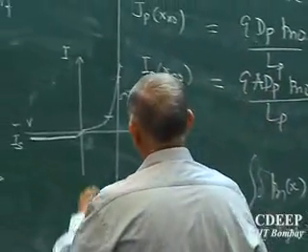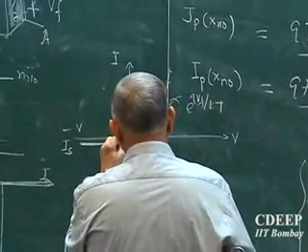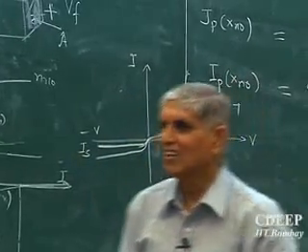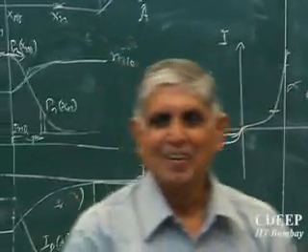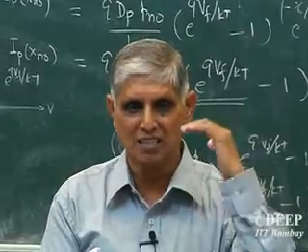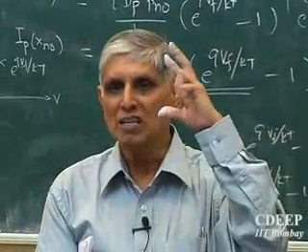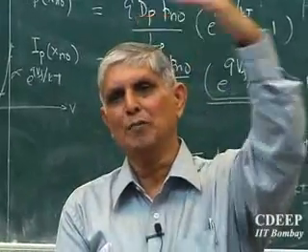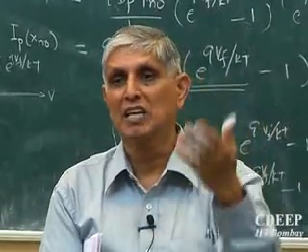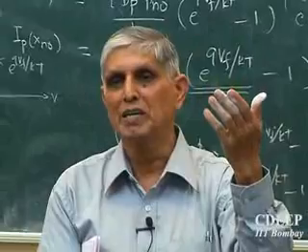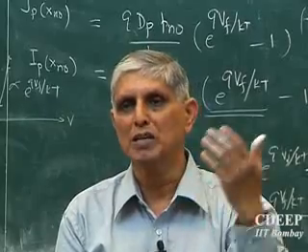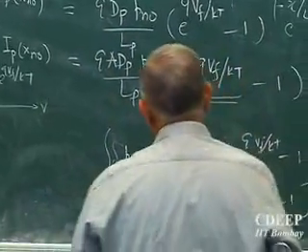But I showed you yesterday, or told you, or maybe earlier, that it is actually not so. The current is increasing very slightly. That means there is a voltage dependent term additional to this constant current. Two currents. Is that point clear? One is independent. But if I see some variation, that means there must be an additional mechanism which is voltage dependent, which is making the reverse saturation current a voltage dependent term. Similar argument I figure out.